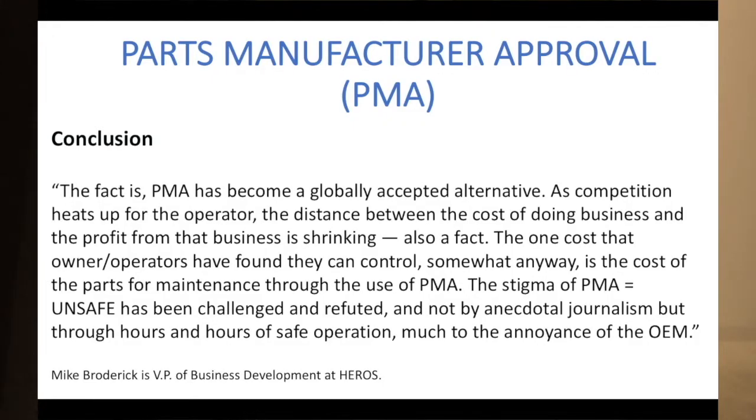The fact is, PMA has become a globally accepted alternative. As competition heats up for the operator, the distance between the cost of doing business and the profit from that business is shrinking. Also a fact. The one cost that owner-operators have found they can control somewhat anyway is the cost of the part for maintenance through the use of PMA. The stigma of PMA equals unsafe has been challenged and refuted, and not by anecdotal journalism, but through hours and hours of safe operation, much to the annoyance of the OEM. Well, I also subscribe to this statement.